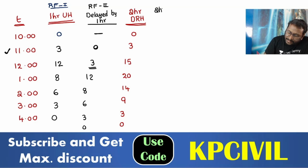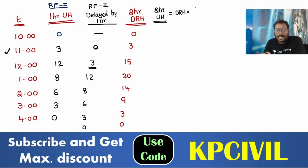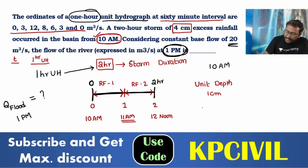From this, I can write down the 2 hour unit hydrograph ordinates. 2 hour unit hydrograph ordinate is equal to DRH ordinate into D by T. What is D by T? Total duration is 2 hours. D is equal to 1, because the unit hydrograph is given for 1 hour.